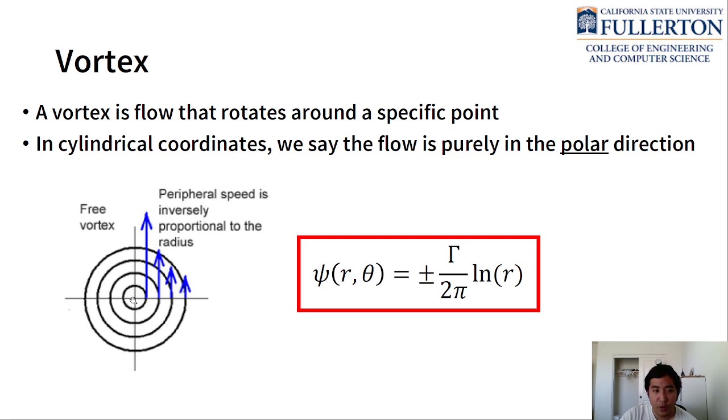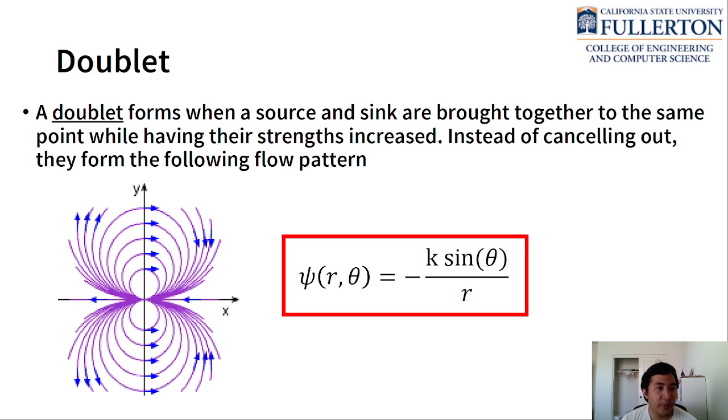The middle of the flow obviously is not going to be irrotational because that's spinning, but if you sit along the flow elsewhere, because the flow has this property, you'll rotate along with the flow, but your body itself will not rotate, which is how we define irrotationality. Okay, so the last basic flow that we usually use in potential flow is called a doublet.